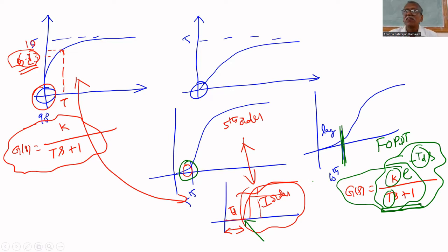The level transmitter will give 3 to 15 psi. PID controller output will be 3 to 15 psi. Input to the PID controller is 3 to 15 psi. Everything is working in pneumatic signal. That time he found a formula; we have so many sophistications now, but we won't find anything better.